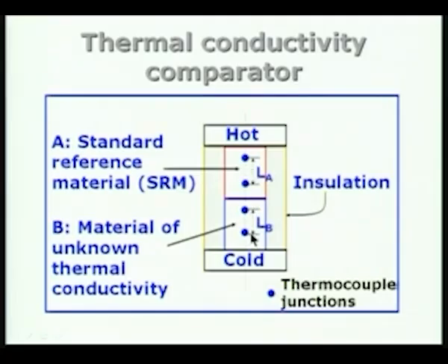a specimen B of material whose thermal conductivity is not known, with the same diameter as the standard reference material. Put them together, stack them like this, one above the other, insulate on the lateral side so that there is no heat loss from the lateral direction, and subject it to a temperature difference, high temperature at the top and the low temperature at the bottom.